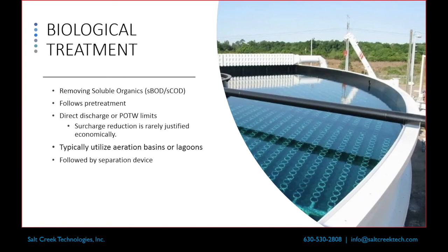So your picture there looks like there's a clarifier with some packing in there, or what is that? So that's a fine bubble aeration system. Oh. Yeah. You probably rarely ever get the chance to see that, because most of the time there's biological material. This was on commissioning, so you can actually see the air grid in there. Oh, okay. I think this is actually, so we work with Westech, and I think this is one of their biosystems that does have a clarifier in the center as well.